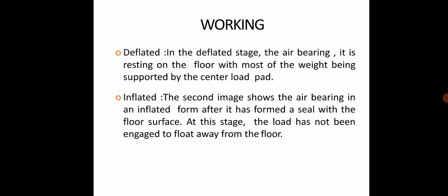Working. Deflated: in the deflated stage, the air bearing is resting on the floor with most of the weight being supplied by the center load pad. Inflated: the second stage shows the air bearing in an inflated form after it has formed a seal with the floor surface. As seen, the load has not yet been engaged or floated away from the floor.